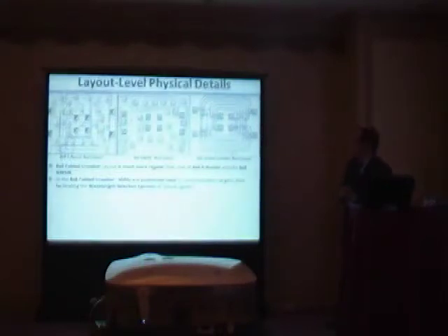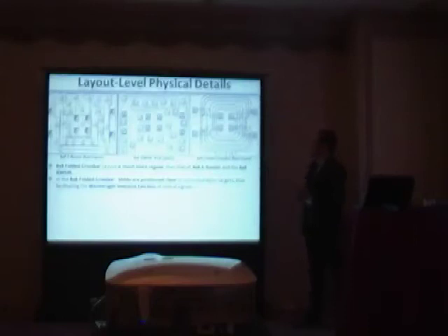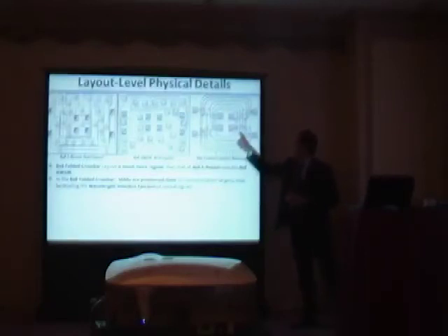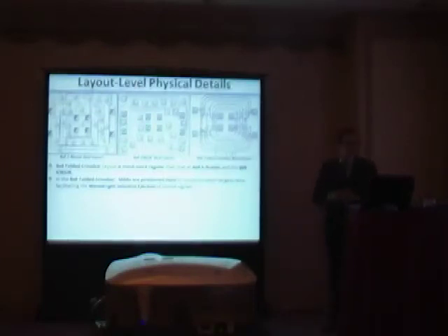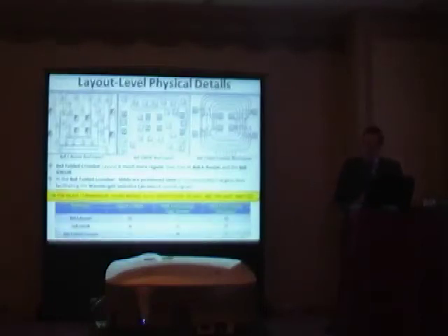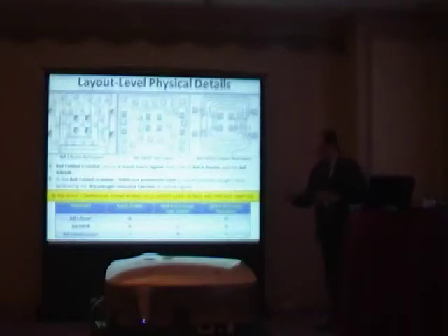Here we compare all real layouts across all topologies, and notice that this layout is certainly much more regular than those of the other topologies. And even here, micro-resonators are positioned close to communication targets, thus facilitating the ejection of optical signals. In this table, we compare these topologies in terms of micro-resonators and crossings in the critical path, considering the logic scheme and its physical implementation.